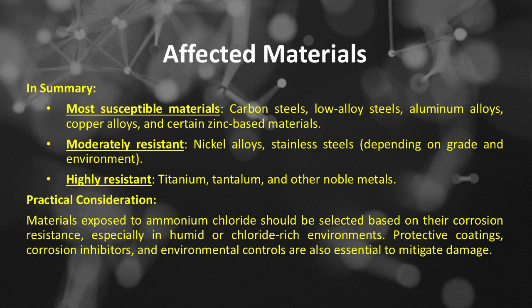In summary, most susceptible materials: carbon steels, low alloy steels, aluminum alloys, copper alloys, and certain zinc-based materials. Moderately resistant: nickel alloys and stainless steels, depending on grade and environment. Highly resistant: titanium, tantalum, and other noble metals. In practical consideration, materials exposed to ammonium chloride should be selected based on their corrosion resistance, especially in humid or chloride-rich environments. Protective coatings, corrosion inhibitors, and environmental controls are also essential to mitigate damage.